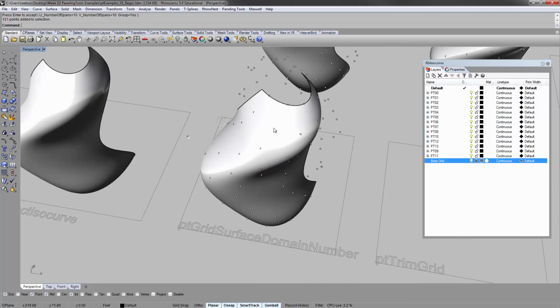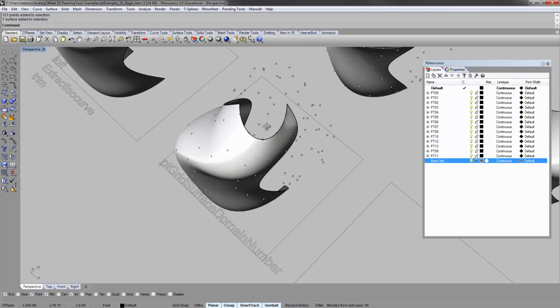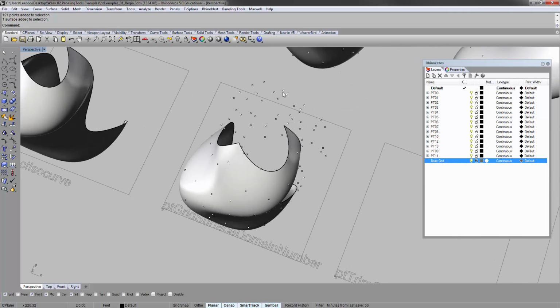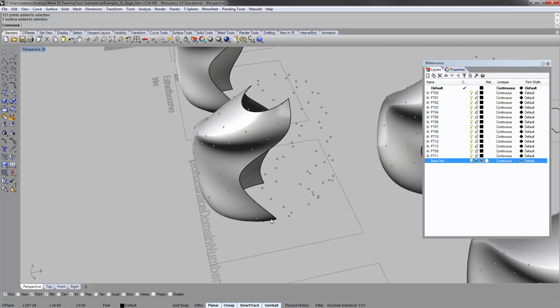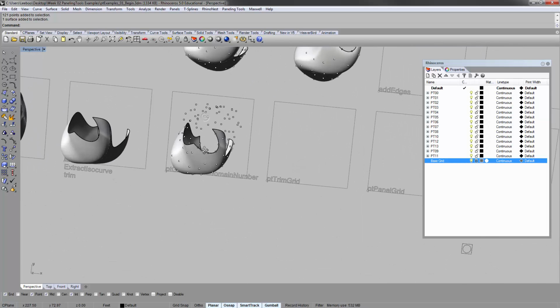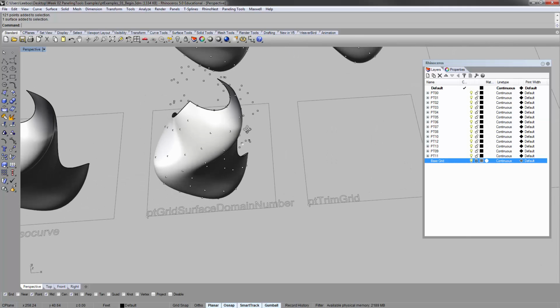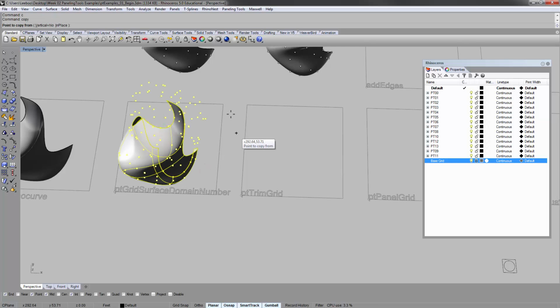And these are based off of the surface. Now, remember that because we trimmed this, right? So you'll see that the subdivision still works off of the whole logic that any trimmed surface in Rhino is still part of a complete surface, right? And so when you subdivide it using a command like this, it will also assume that the whole surface is there, not just what you're showing, okay? And that's one of the things you have to understand or realize. Okay, so let's copy this over again.